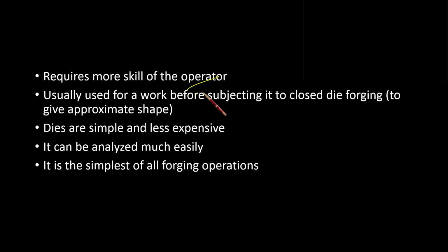Require more skills. Simply, you cannot get exact dimensions. Even when you are doing forging the first time, open die forging basically, you will see that you are not able to get even close to the dimensions which you wanted. That is not good, but it is a little bit less expensive. And it is good for analysis, what kind of forces and how much, all those things are easy for this one.